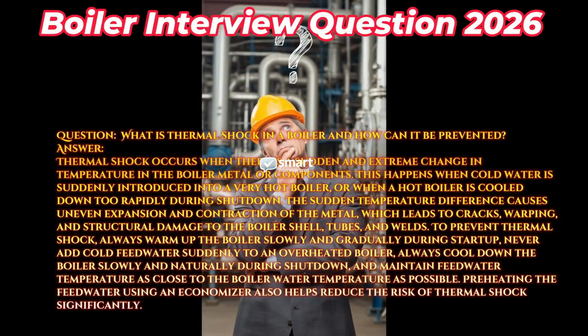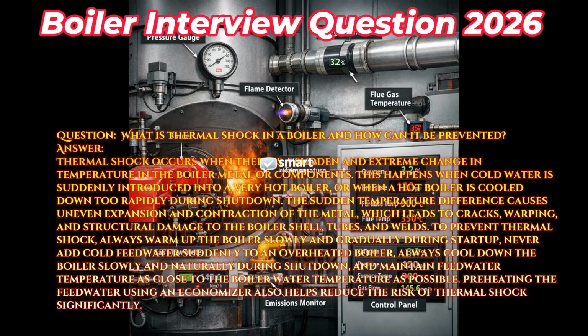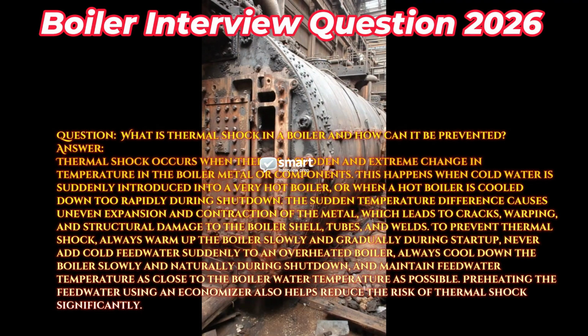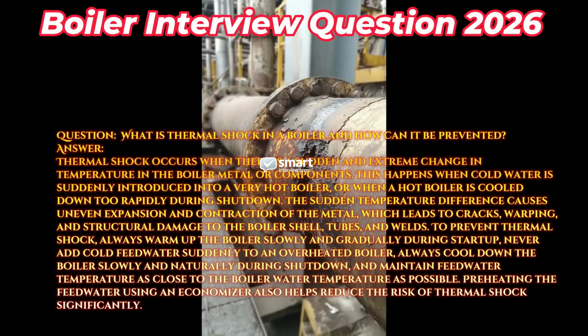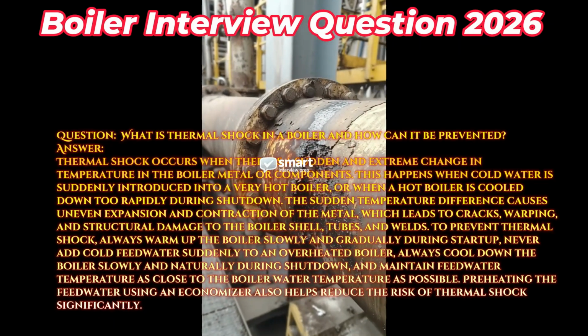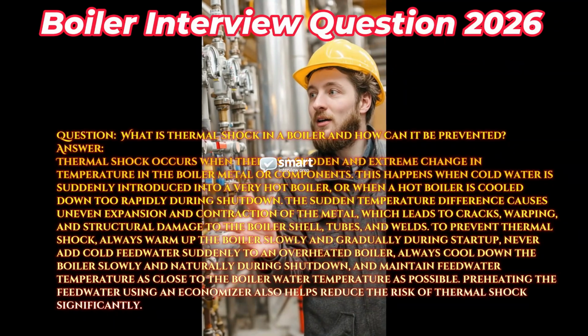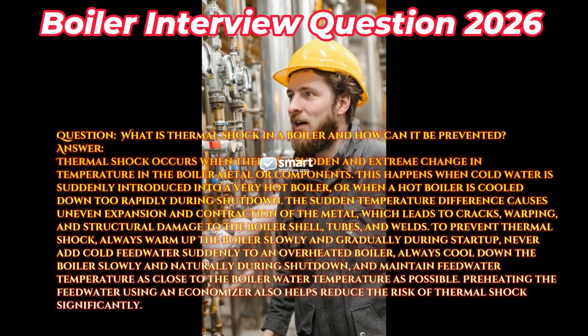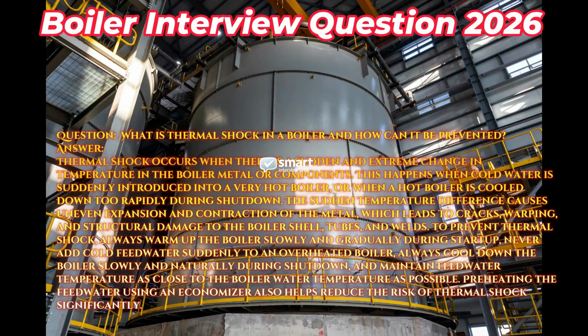Question: what is thermal shock in a boiler and how can it be prevented? Answer: thermal shock occurs when there is a sudden and extreme change in temperature in the boiler metal or components. This happens when cold water is suddenly introduced into a very hot boiler, or when a hot boiler is cooled down too rapidly during shutdown. The sudden temperature difference causes uneven expansion and contraction of the metal, which leads to cracks, warping, and structural damage to the boiler shell, tubes, and welds.